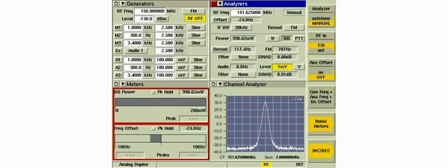The radio is keyed, and the instrument is measuring the RF power and transmitter frequency offset. The numerical and bar graph data tell us that the transmitter power is 998.62 milliwatts and the frequency offset is -24 Hz. These readings may or may not be within specification of the radio.